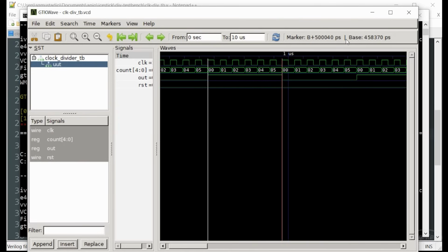In fact, when you start looking into complex designs, you will often find unit tests written for the individual modules for that complex design. And it can get even more complicated where you can start scripting your test benches and having your test benches automatically verify what it's expected to see in the modules.